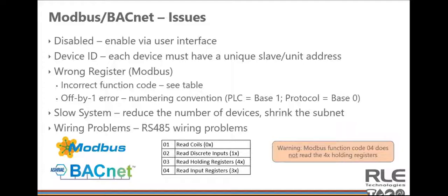All right, so continuing kind of chronologically in this installation process, one of the final things that could be across any of our product lines is you might want to integrate the data from your controllers back into a BMS or BMS system. So absolutely one of the first things you want to do is just to make sure the proper protocol is enabled on both like the master and the slave devices. You also want to make sure that device ID is unique so that you're getting the correct response and also not duplicate responses from your devices.